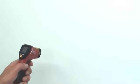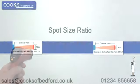Infrared thermometers are equipped with sophisticated optics that measure radiated heat. All objects have the ability to absorb and emit radiated heat, but at different values. There are two important factors that can drastically affect the accuracy of a measured value. One being the spot size and the second being emissivity. I will deal with the spot size first.